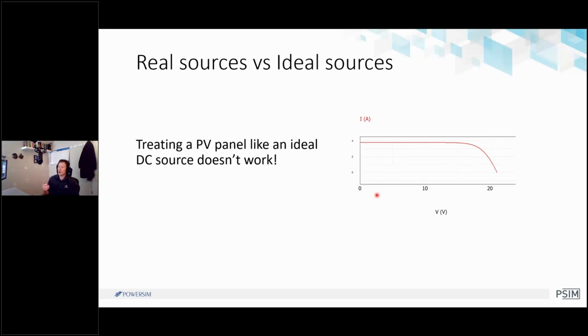I've also seen instances where someone is doing a microgrid, and they design their three-phase PFC, for example, off of an ideal or infinite DC three-phase source. Then they connect their PFC to a microgrid-developed source, a three-phase source developed off of switching inverters or active rectified PMSMs or something like that. And all of a sudden there's an interaction between those things that wasn't considered before.